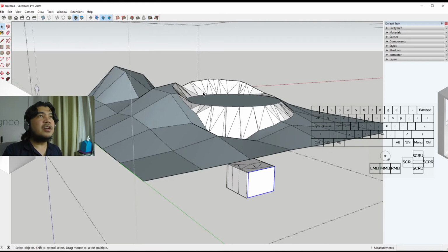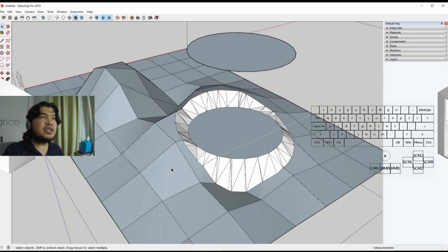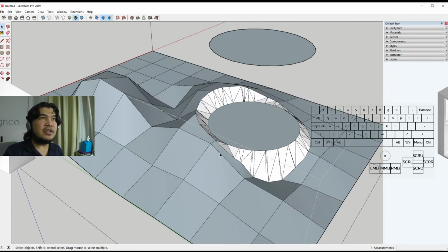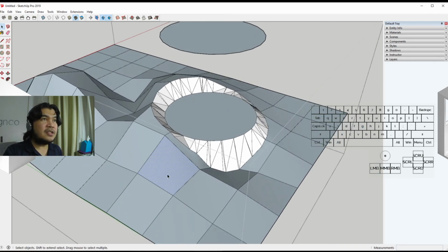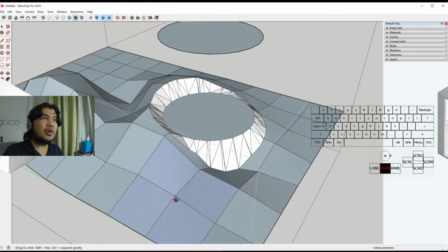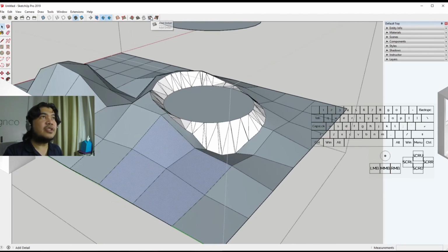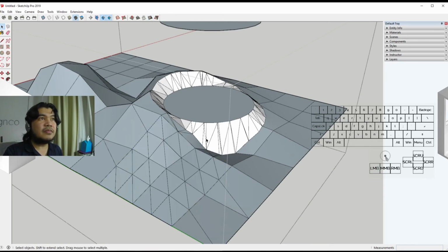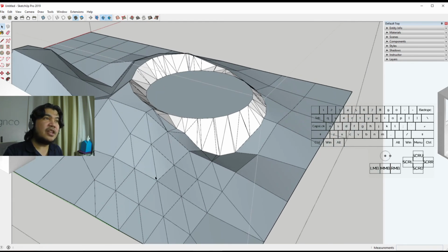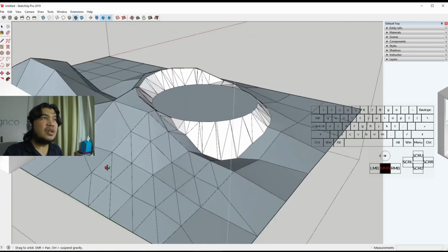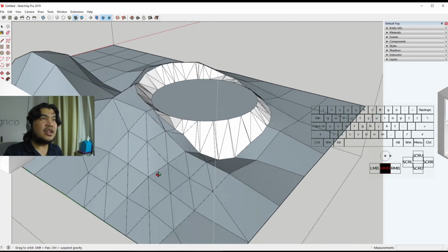What else do we have here? Oh, this one. Add detail means resolution will increase in that particular position. When I talk about resolution, that basically means the number of vertices and edges that you can work with. For example, we choose this. Let's choose these four squares here and then add resolution to it or detail. What happens is a new square has been formed inside of it, and all of those areas around it